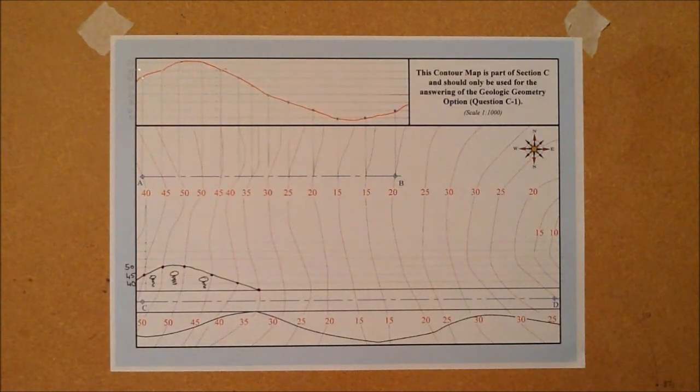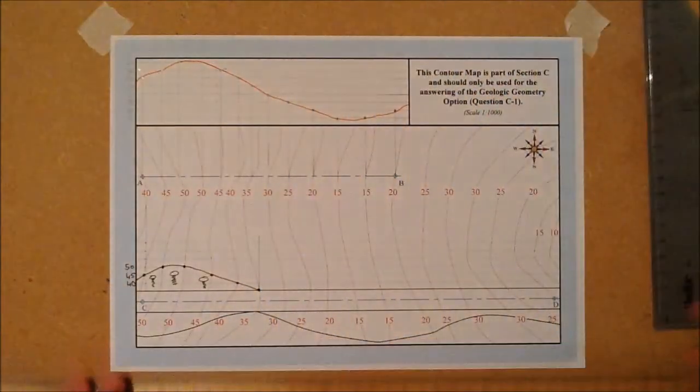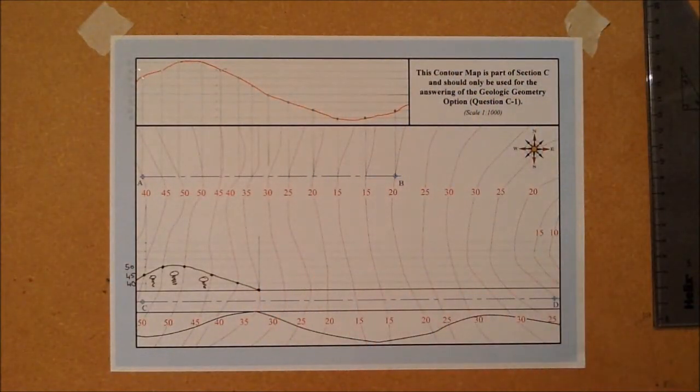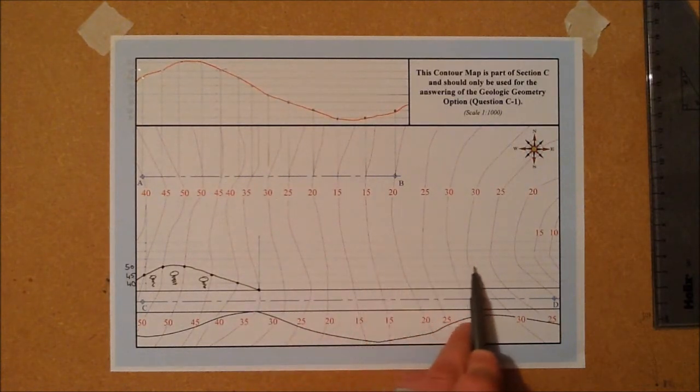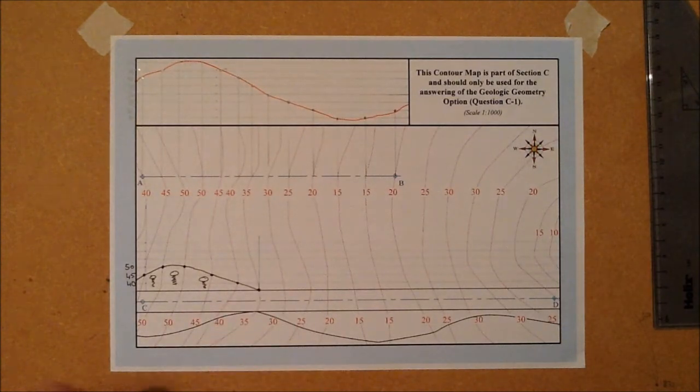Getting back to the question, I'm going to need to plot these points. I'm going to draw another line here from this point on in order to put in our measurements of the contours from here over. Because we know this is the point 35 on the road where this cut meets the road, from here on in it's going to be an embankment. The land around the road is going down to a lower altitude, so if we're coming out in 5 meter intervals, remember we're going down 5 meters lower each time.